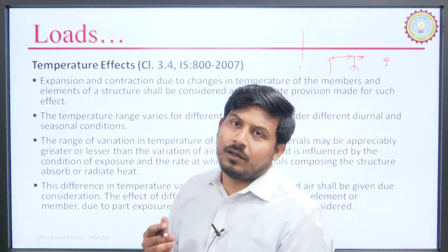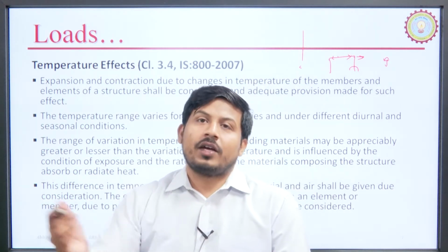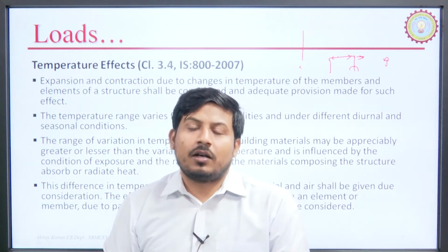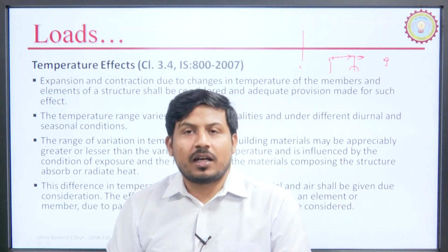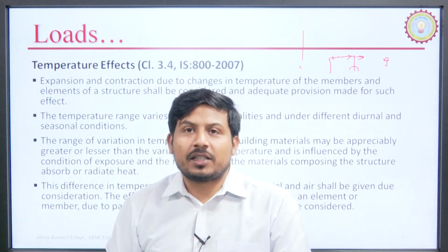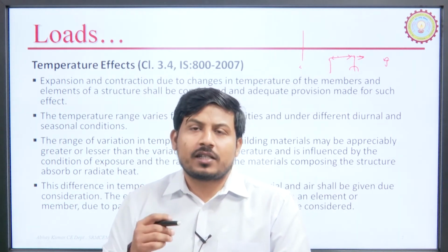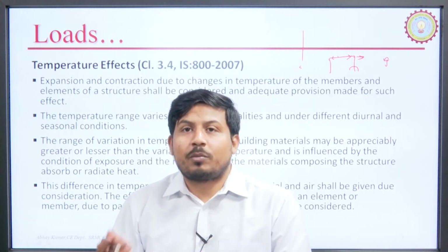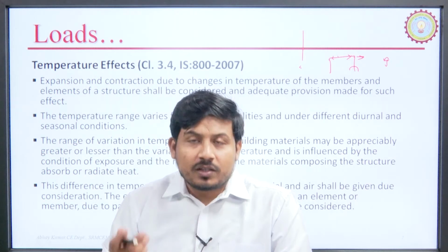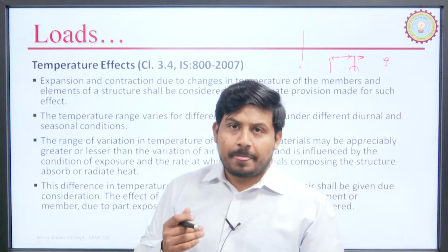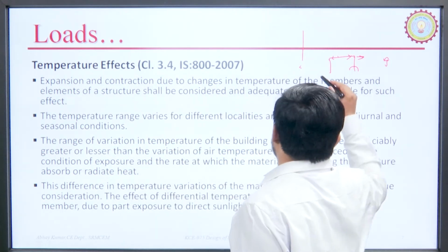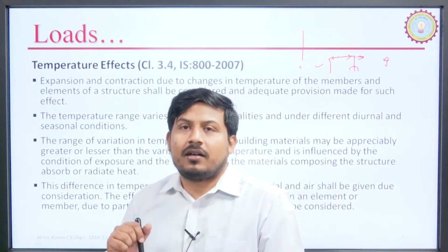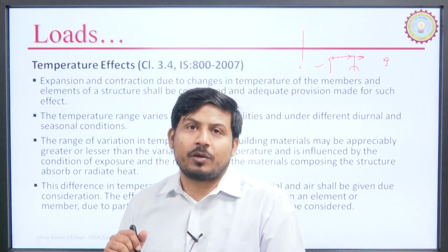So, there are various places in India also where the temperature variation is very high. For example, if I talk about Lucknow only, or the northern plain of India, we can see there are many places where the temperature may go up to 45 degrees Celsius in summer, and during winter nights, the temperature may go down to 0 degrees Celsius. Okay. So, this huge variation will definitely cause this kind of problem, and while designing any steel structure, we must consider the various temperature effects and the different forces which will come into the picture because of the temperature.